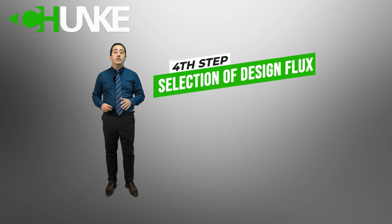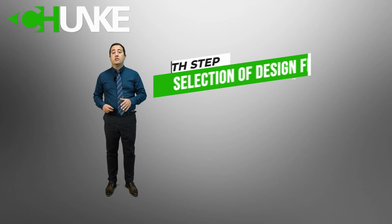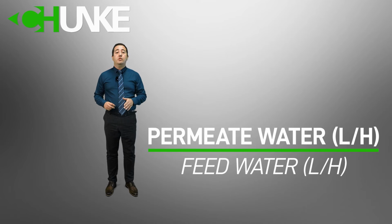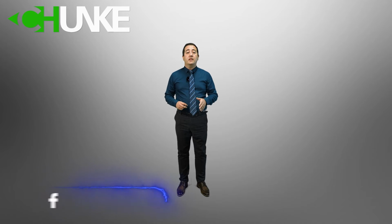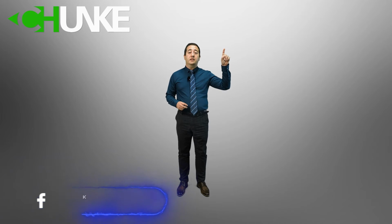Fourth, selection of design flux. Reverse osmosis systems are designed with regard to specific permeate flow rate and recovery rate. Recovery rate means how many percent of feed water becomes permeate treated water. The factor which has the greatest influence on the membrane system design is the fouling and scaling tendency of the feed water. To learn more about fouling and scaling, I suggest you watch our video in the explanation section, and here I share the link with you.